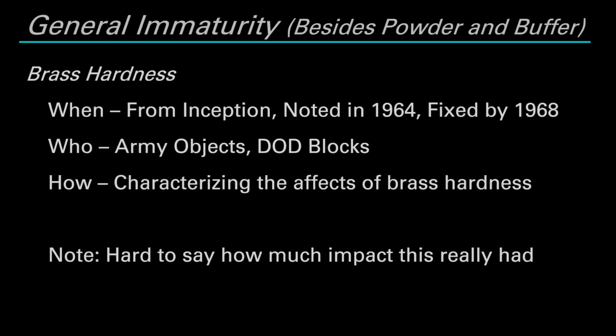Eventually, the AR-15, spoiler alert, becomes that permanent replacement. But at the time that the DoD is rushing the adoption of this rifle, they're rushing it because they want to have something else here in 2 or 3 years anyway. And in that context, you're best able to understand why they would rush something like not having chrome lining, or why they would rush something like not having a hardness spec for cases, or why they would rush something like the buffer being underweight, or not actually having a fully mature cartridge powder design yet.